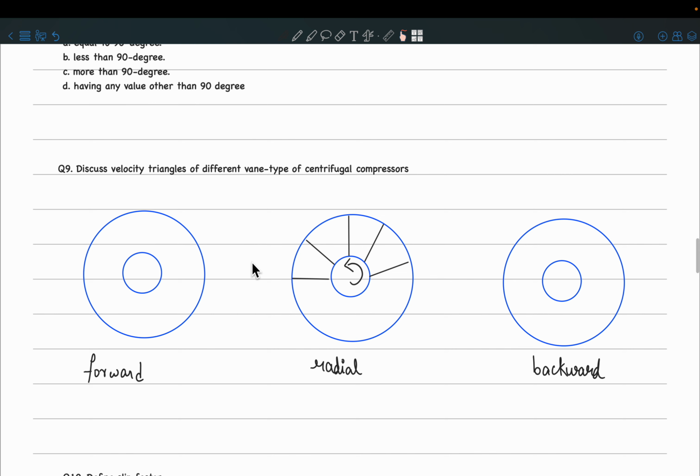But now if I twist the blades, right? So let us say that we are going to rotate anti-clockwise, and the twist of the blades is such that the twist is in the direction of the rotation, like this. Then this is called a forward lean, because the twist of the blades is in the forward direction. Forward as in the direction in which the rotation is happening. So this twist is what is defined as the forward or the backward thing.